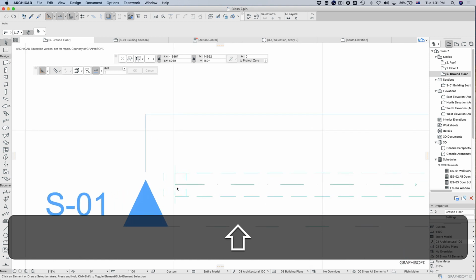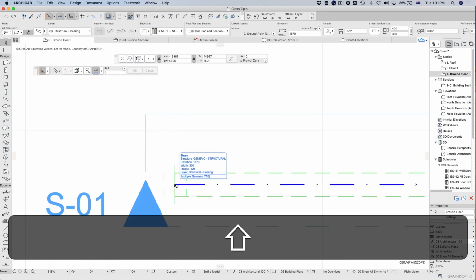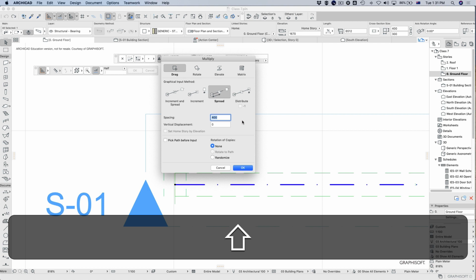And you can actually see that's what I'm doing here. If I hover over here and select, I've selected the beam, not the hole. If I hit Tab, in fact you can see at the bottom there it says multiple elements, Tab. So when you press Tab, I've got hole and beam. Bam, got them. Command U. Get used to those keyboard shortcuts.